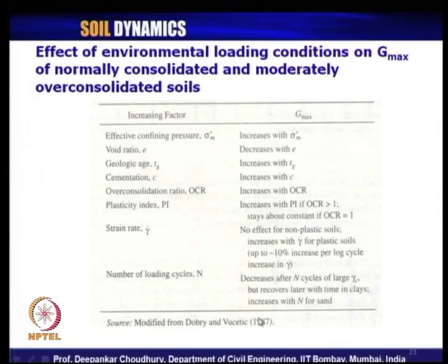That is the source. Now, what happens to the strain rate? You know that all tests, not only the dynamic test, also the static test, like if you take triaxial test or direct shear test, are strain rate based. That is, if you change the rate of application of your strain, obviously, you will get different results or different modulus of the soil. Similarly, for the dynamic test also, if you keep changing the application of your strain rate,